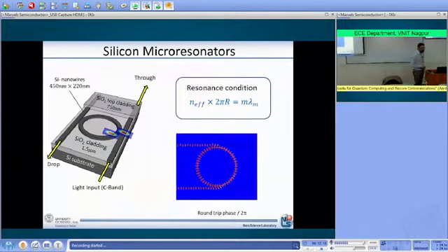And now, if you get this coupling, what you can get is the fact that your light is coupled, okay? It's coming from the bus waveguide, and is here. So this is an FDTD calculation of the optical field that is inserted into the bus waveguide. Then here you see that you have an overlap between the mode of the optical field and the mode of the microring resonator, and so you have a coupling between the two.